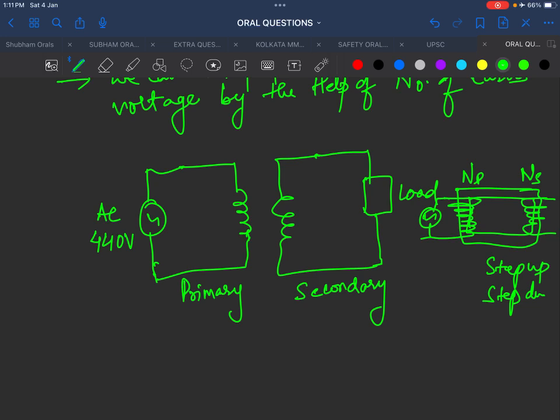So when we connect this conductor core with the power supply, current flows there. That is the primary current, which I denote with I1. Due to the primary current there is a flux generation, which is linked with the secondary circuit, because due to the mutual inductance the flux links with the secondary circuit, and that is a magnetic field which is rotating in nature.